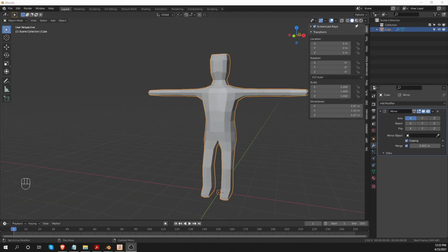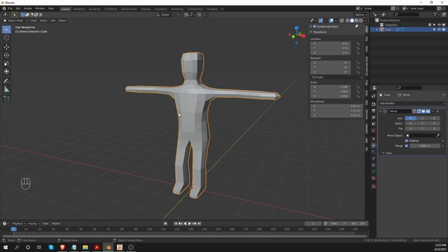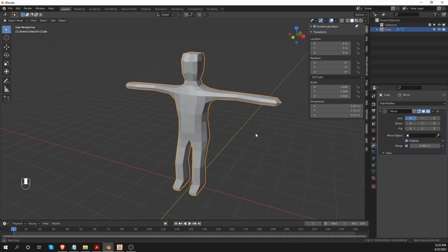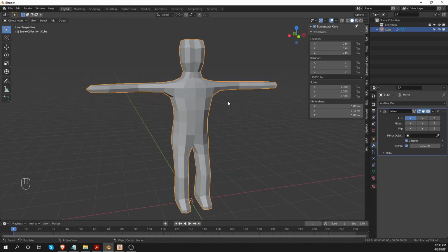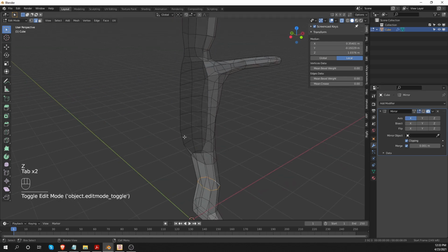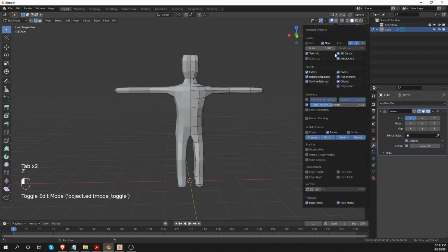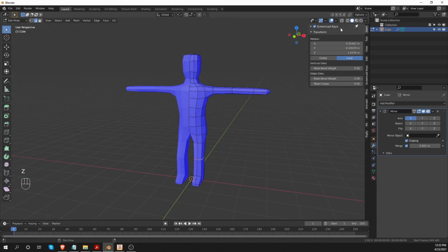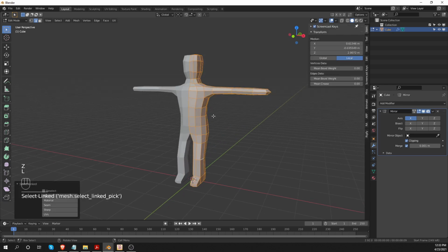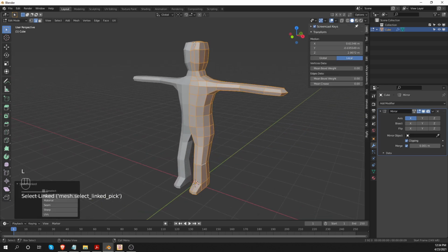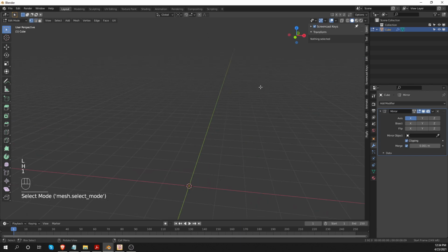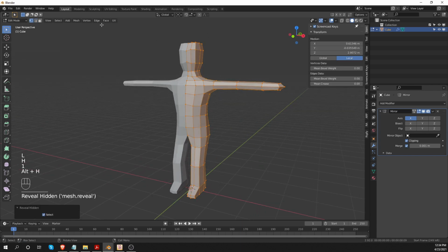Okay, I swear that that's not the level of my actual modeling skills, but the point here is that I have an object that is symmetrical, the mirror modifier is applied correctly, there is no polygon in the middle, the center line is correct, normals are okay, and if I hide this main chunk of the mesh, I won't find any floating geometry. If I try to merge by distance, Blender would tell me that 0 vertices were merged because there is no overlapping geometry and so on.